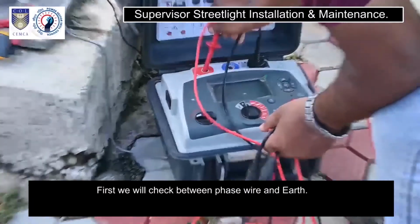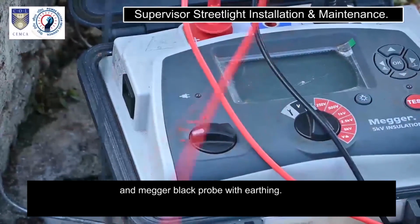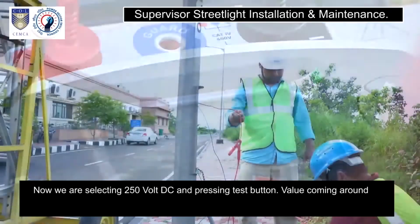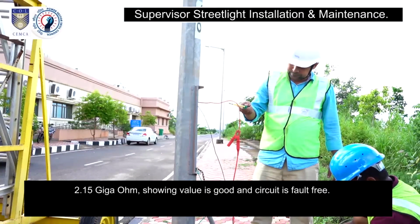First we will check between phase wire and earth. We have connected the red probe of the megger with the phase wire and the black probe with earthing. Now we are selecting 250 volt DC and pressing the test button. Value coming around 2.15 giga ohm. Showing value is good and circuit is fault free.